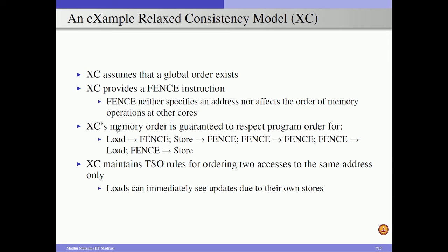And so whenever we want to enforce the ordering among instructions, we can separate this pair of instructions with a fence instruction. So effectively, if you have a load and a store, and if you want to execute this load first and after that the store, then we will insert a fence instruction between this load and store. So effectively, once we have a fence instruction between any pair of memory instructions, all the instructions before the fence should be completed before we execute any instruction following this fence instruction.